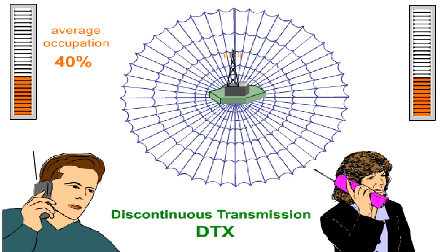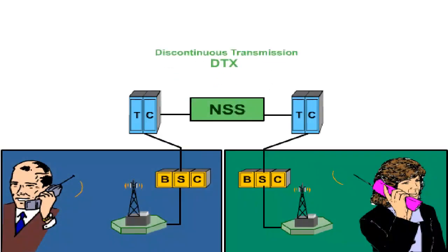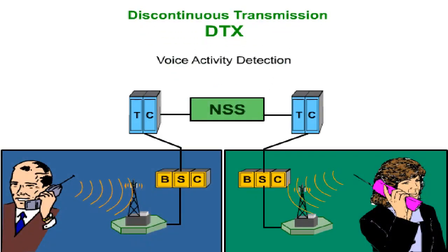Discontinuous transmission, or DTX, is a remedy to this problem. In DTX, a function known as voice activity detection switches off the sender of a mobile station whenever there's no data to be transmitted. During speech pauses, a stop gap in the receiver, which in the uplink is the corresponding transcoder element in the TC, must simulate a functioning channel for the user.